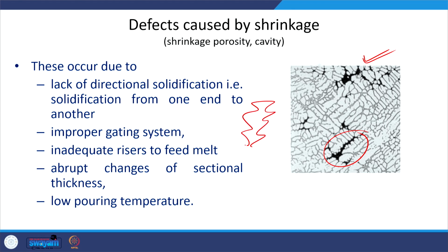This is how we can identify it, and this happens especially when the solidification is not directional. It is not starting from one end and progressing to the other, but it is progressing from different directions and leading to unfilled sections somewhere in between.